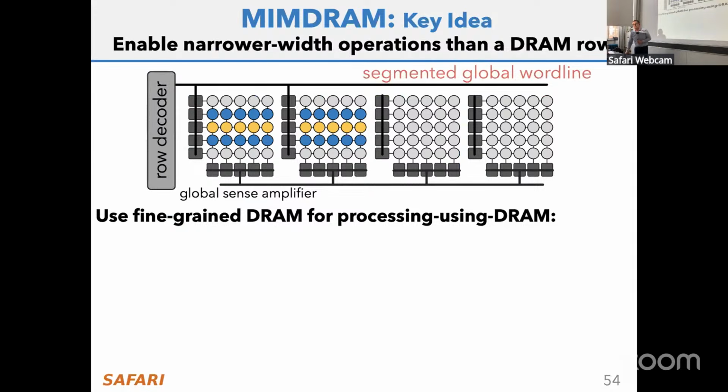make it more flexible. And one of the key issues in this sort of block bitwise execution is what is the granularity of execution? Meaning, whenever you do a triple row activation, how many bits are you operating on? Is it 64,000? What is the size of the row, for example? In prior work before MIMDRAM, the size of the row was the granularity. If it's 64,000 bits, if it's 64 kilobytes, it's 64 kilobytes of data that you're operating on in a bitwise manner. Right? If it's 8 kilobytes, it's 8 kilobytes. Both of these are very large numbers, actually.